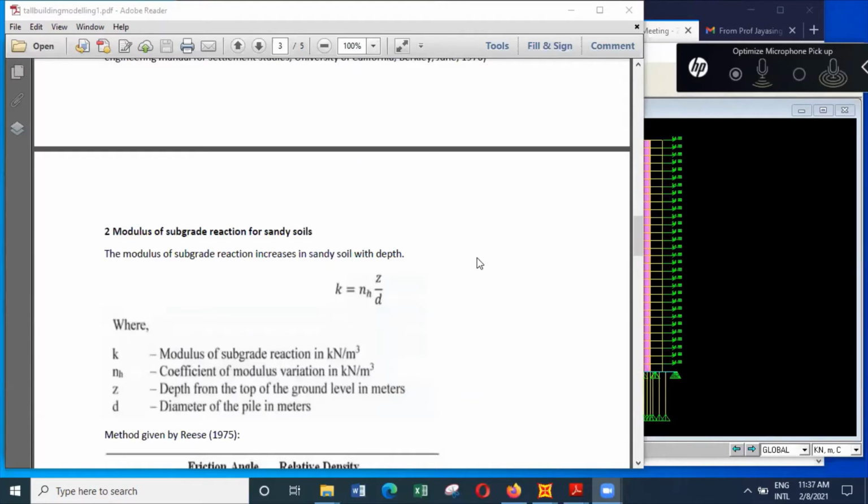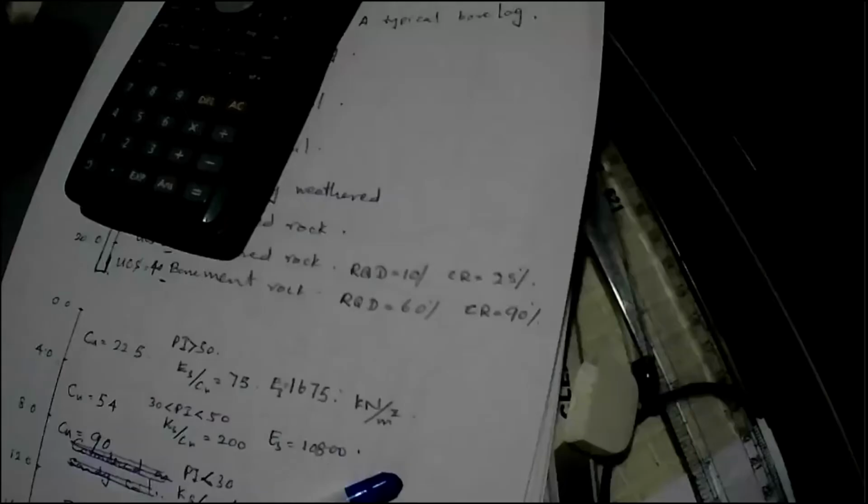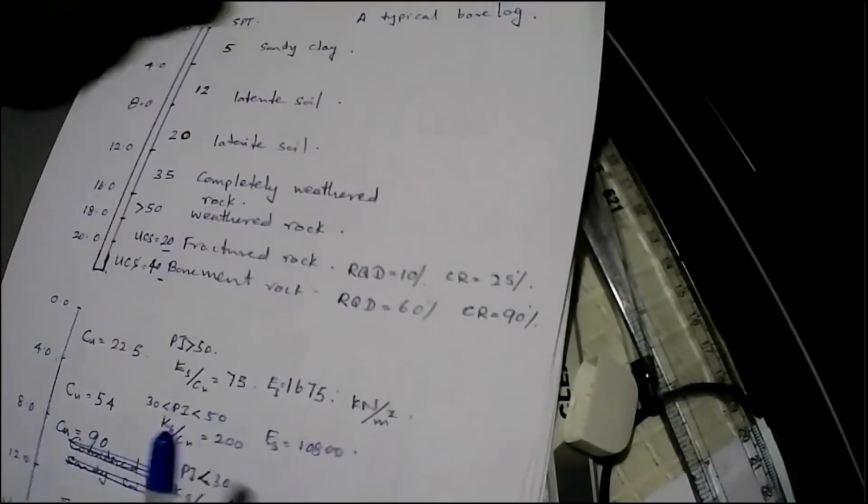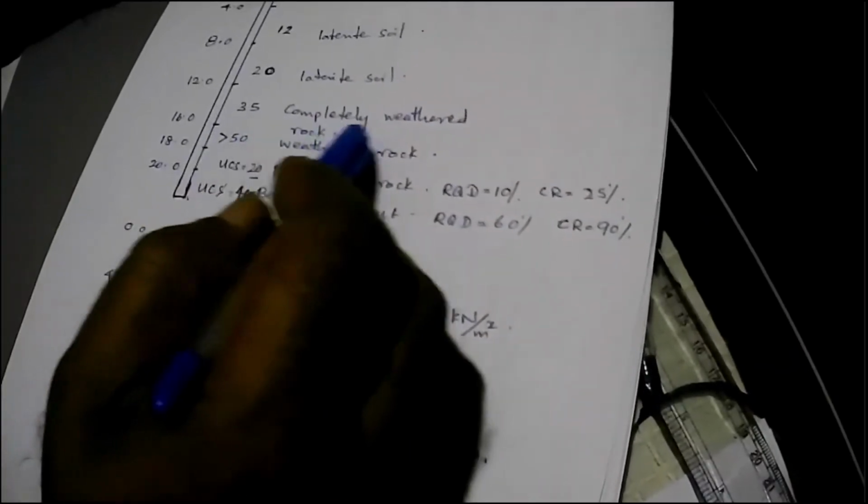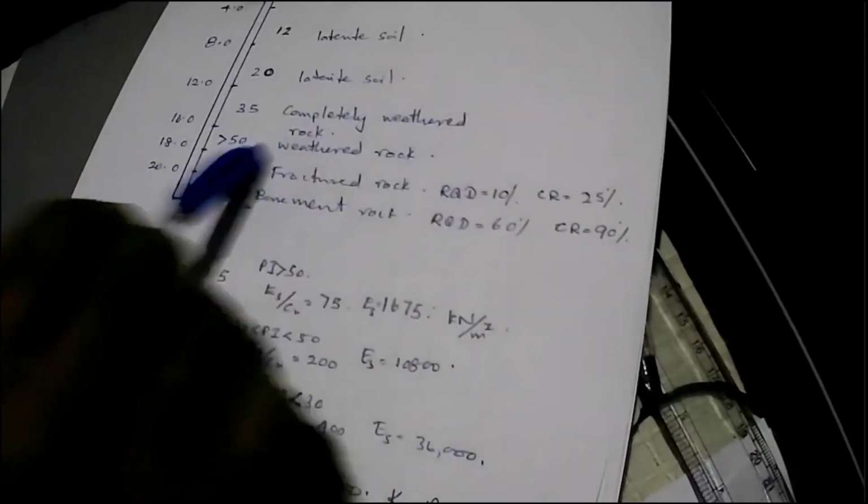In sandy soils, the horizontal subgrade reaction is not constant. It is actually increasing. Now you have to decide what you mean by sandy soils. In reality, sometimes you can encounter something like completely weathered rock.